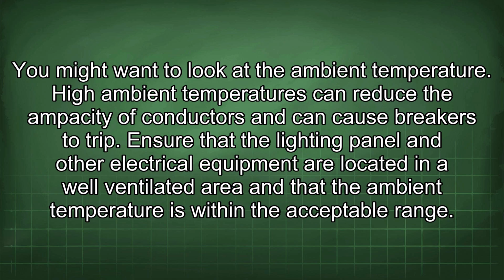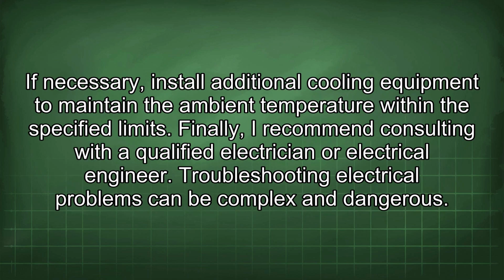Ensure that the lighting panel and other electrical equipment are located in a well-ventilated area and that the ambient temperature is within the acceptable range. If necessary, install additional cooling equipment to maintain the ambient temperature within the specified limits.